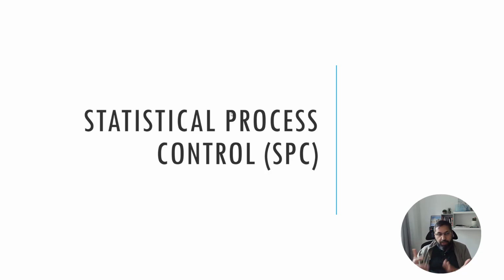Unfortunately, in many courses and textbooks, they go straight into process control, and then process capability is given like a footnote or just a page at the end of the chapter, which is completely backwards, because why would you want to control an incapable process? It doesn't make sense. So you have to first identify if the process is capable or not.